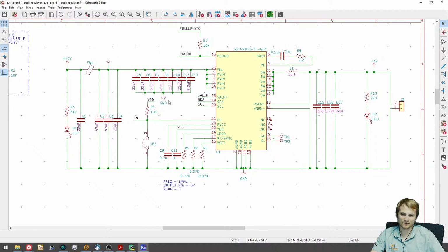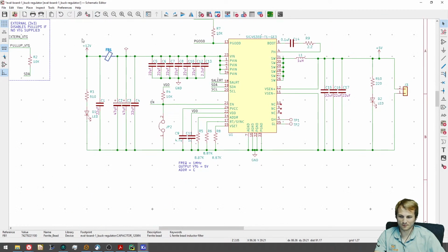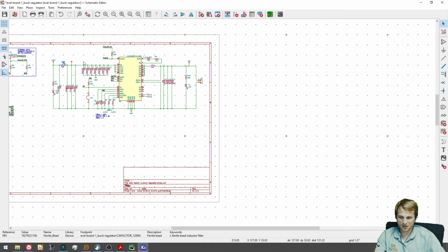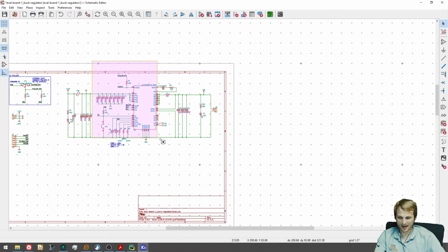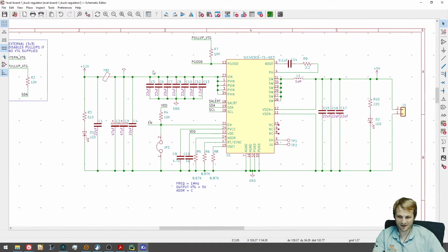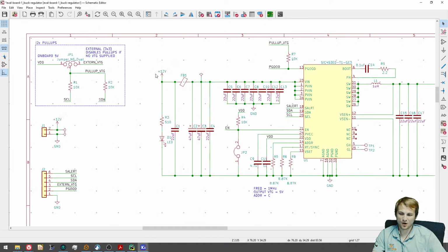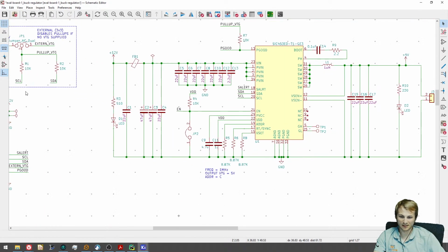All of that comes from interplanar capacitance between the planes, which if you do this, you completely remove all of the planes. So yes, if you were to add a big plane on this side of the ferrite with ground, that would work, but you're much better off using your ferrite on the other areas to separate the analog side, which is slower, or to keep noise from leaving the board.